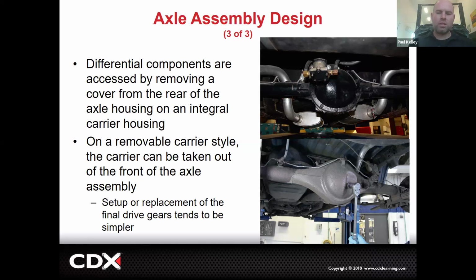By the time that bearing starts to make noise, you got to do an overhaul, and that could be thousands of dollars. So it's very important that we check the fluid level periodically, and we're inspecting for leaks and whatnot. This one's nice because it's got the plug on the back. This is a Toyota, actually. This type, sometimes the plug is on the side.